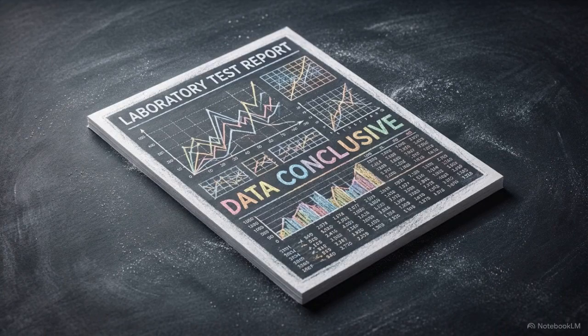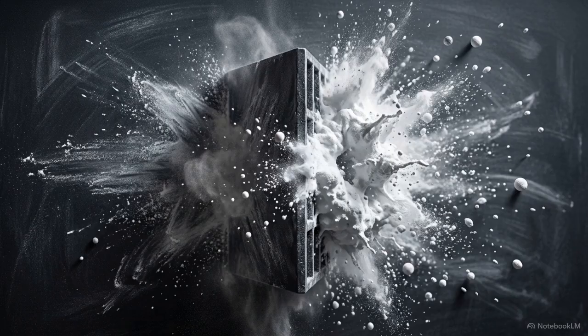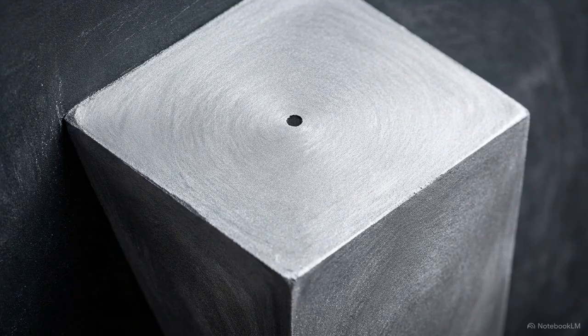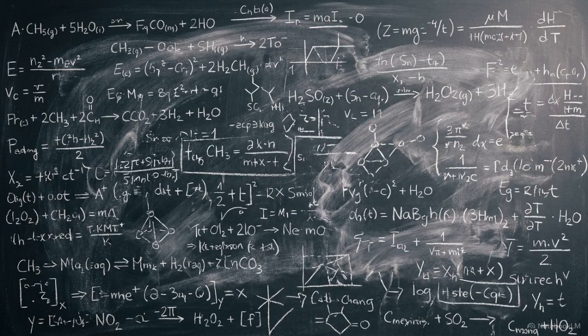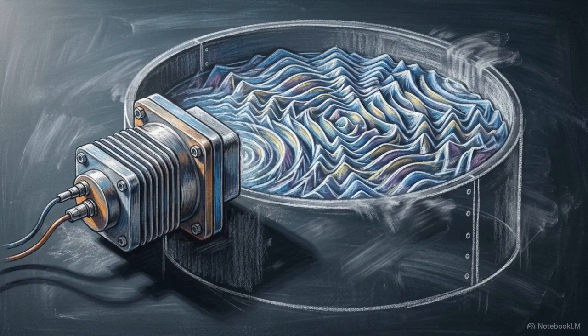The quantitative data is conclusive. By violently scouring the surface, internal porosity is driven down to 0.03% of the total coating volume, securing the structural density required for sensitive applications, like X-ray mirror molds. When the chemical optimizations reach their limits, aggressive physical manipulation takes over to enforce structural perfection.